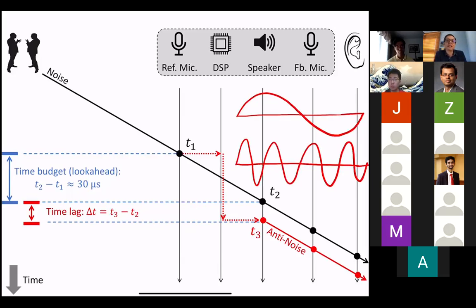if I am delayed by some time, let's say tau, I've missed the deadline by some time tau. How much phase lag am I going to see with the low frequencies and how much phase lag with the high frequencies? Or in other words, should I see more phase lag with the low frequency or more phase lag with the high frequency? It'd be much worse with the high frequency. Yeah. Right? So the higher the frequency, a little bit of delay, a little bit of missing the deadline, has a bigger penalty.